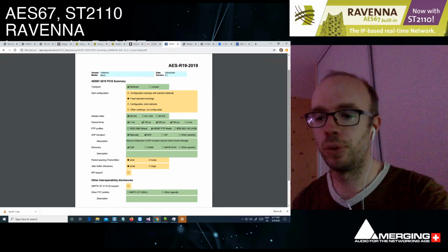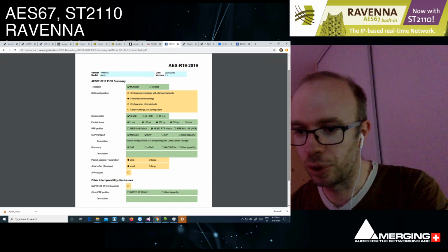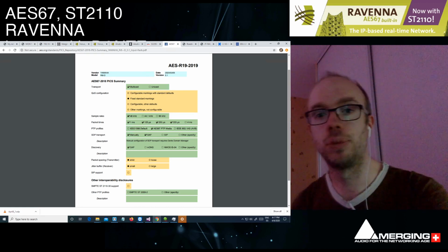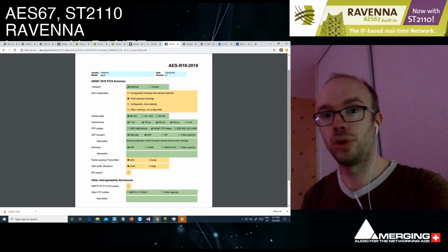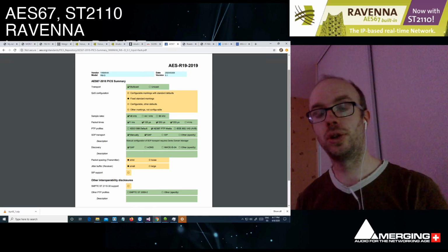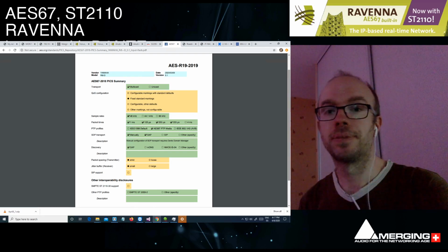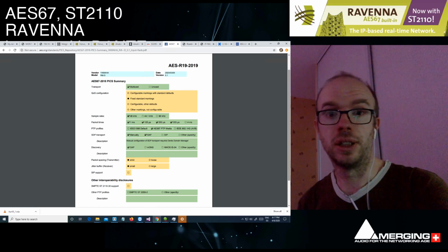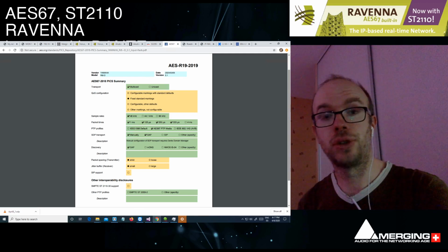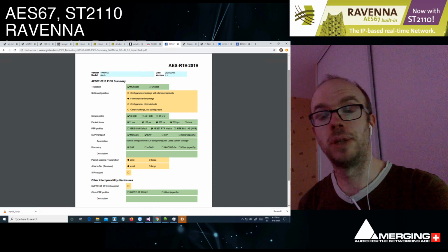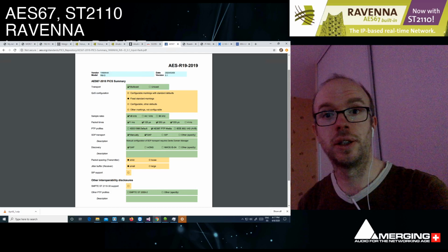So Tibor, you had one more question. Don't you run the risk of auto-assigning, changing the multicast IP address attribute? So if you have a device that changes the multicast address attribute compared to what you just configured, it's either an old device or it's a buggy device. It shouldn't happen. And if you have one example of one manufacturer that told you it's his way of doing things and doesn't consider that a bug, I would be pleased to have a chat with him and to understand why he thinks that way.